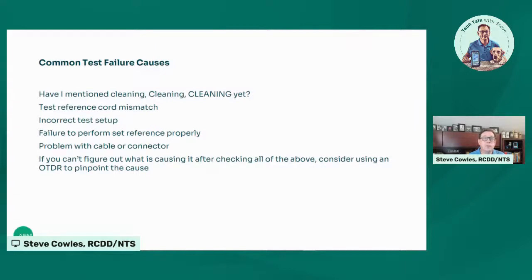I've actually seen cases, we used to refer to it as wavy fiber, where somebody would hook up a pulling grip to the jacket of the fiber and they'd pull the fiber in. And what would happen is, because that grip was attached to just the jacket of the fiber, the actual strands of fiber got bunched up underneath the jacket, and that's what we called wavy fiber, and it was causing some problems. It was causing the test to fail. And that can be avoided.